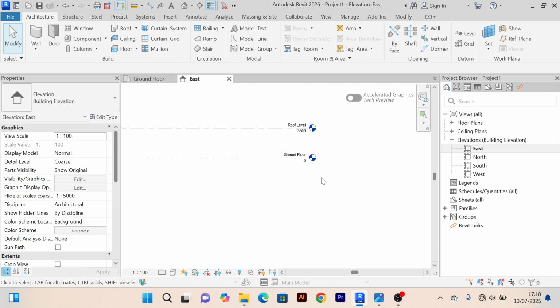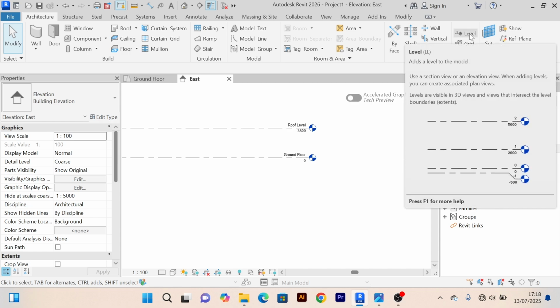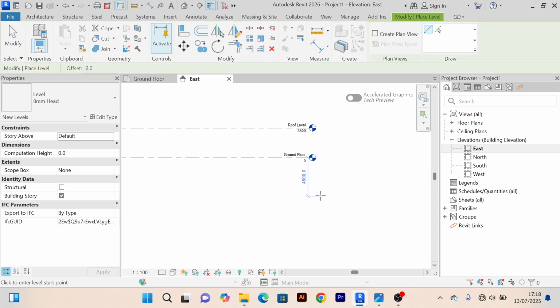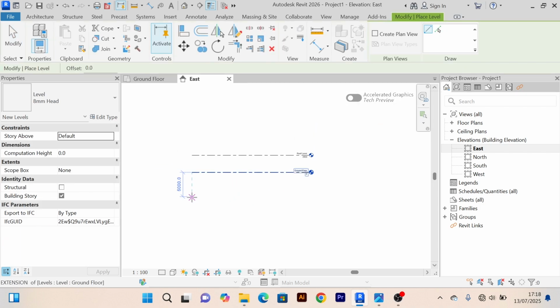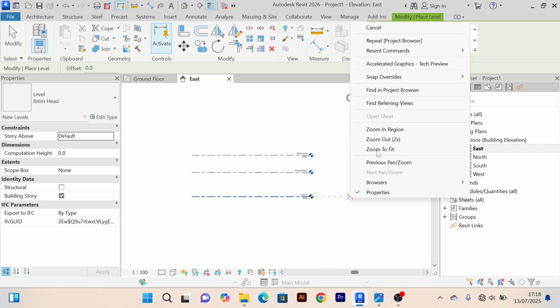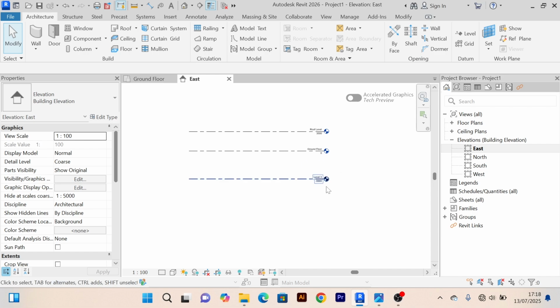So to create a new elevation or new level, if you click on this architecture, which is on our left here, or you just try to browse through this line all the way to this side, you'll see here there's this level button here. The level tool is here. I can simply click on it, then I'll come and start drawing. So I can start to draw from here. I'll just come and leave it here. Then I'll escape until my mouse is free.